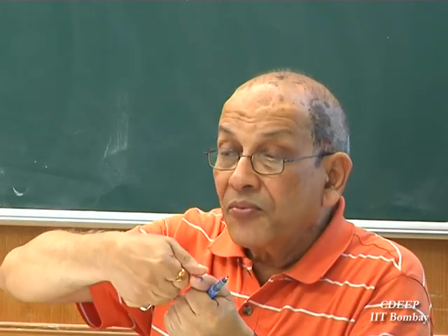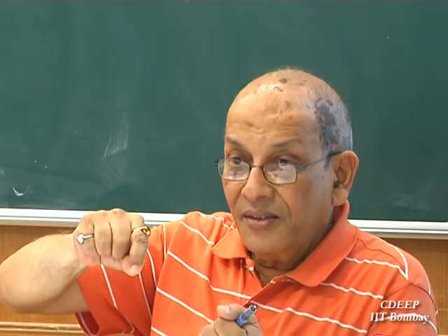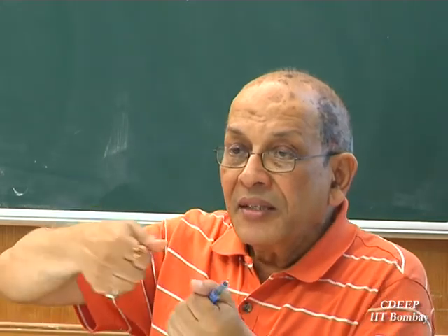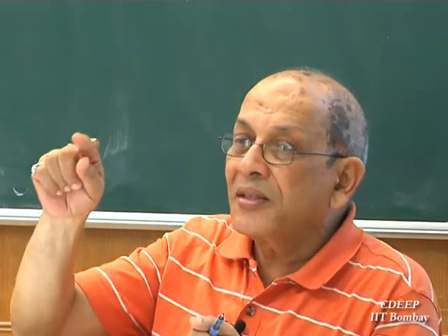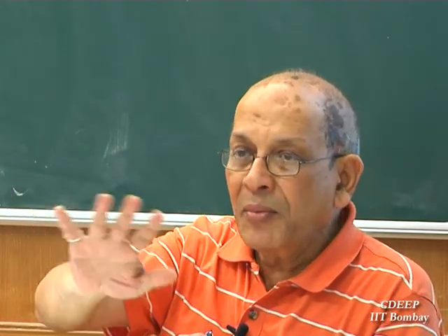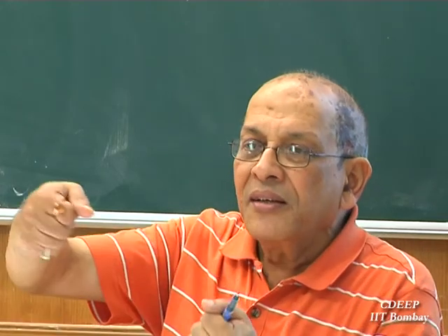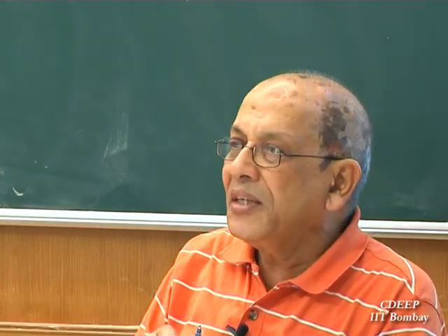Then you can really see whether the steel which you have, supposing this value is coming out more than the sigma y, the yield of steel. You are designing a structure, a beam, and this value sigma 1 is coming more than sigma y. Sigma y means what? Yield.